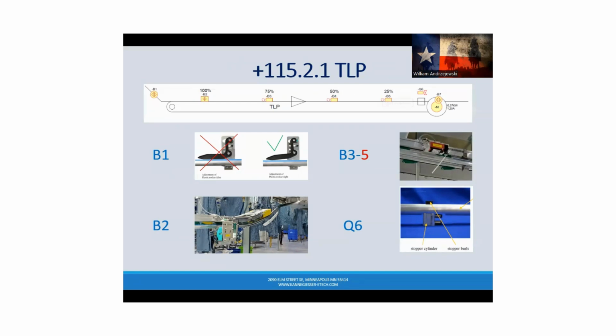You don't necessarily need the manual if you understand the concept of the numbering and you understand the process of one conveyor. So there won't be a B1 and a Q1. Nope, never. What we do is we start off with K0 and we go 1 through 8. Okay, and then if we have more modules on there, what we actually do is go to a K0.1 and we start the numbering off at 21, 22 to 28.